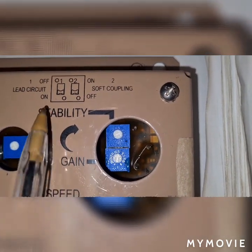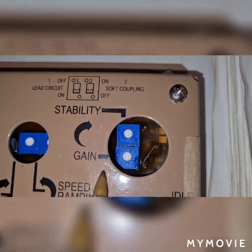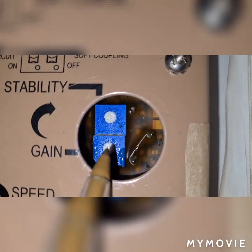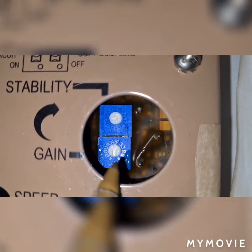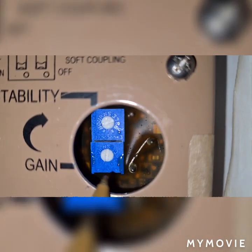So here you will see the stability and the gain. Actually it deals with your governor performance. For gain setting, you also have a potentiometer here, which is labeled BOURNS, then 3, we also have 8 and 6. It was labeled like that.